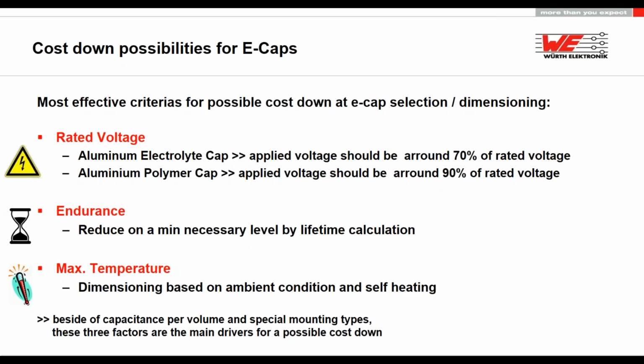So this means if you're maybe running at 350 volt, 450 would be fine. It's not necessary to go for 500 or 600 because it will just increase your costs. But anyway, it could also increase your expected lifetime.